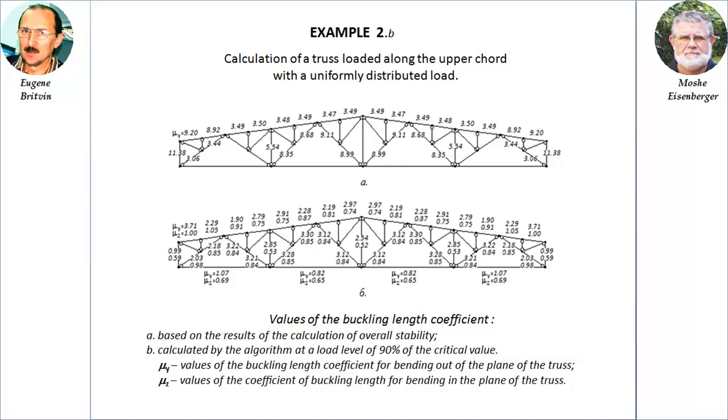First, it should be noted that the local stability checking of rods has nothing to do with the loss of stability. As noted in the introduction, we are actually searching for the limiting value of the compressive force at which the design stress appears in one of the rod fibers. And if the force acting in the rod is below this limit, there is no danger. This limiting force is determined by the rigidity of the rod, its length, and the boundary conditions for the member.